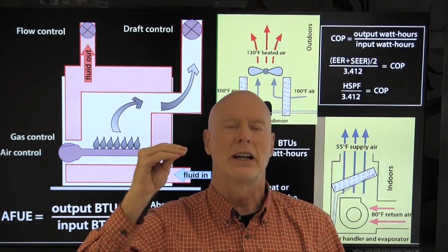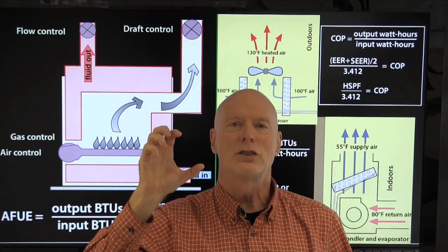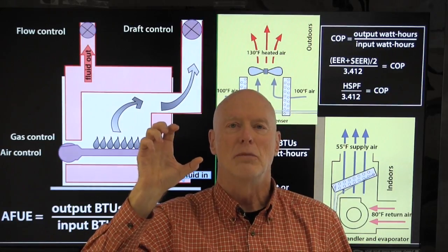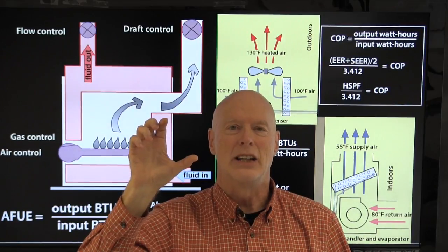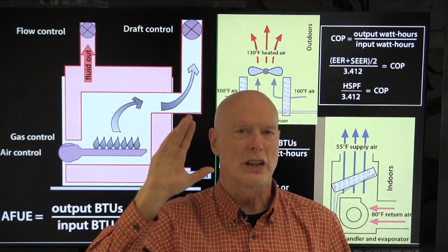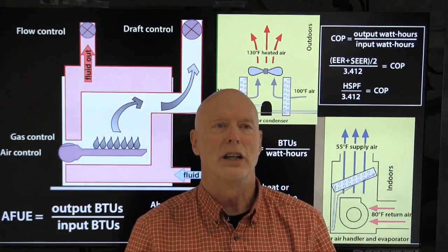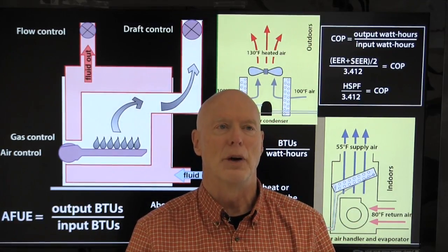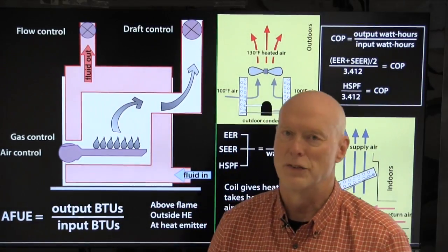The other thing that would indicate a kind of perfect efficiency is a very small temperature difference between the thermostat set point and the heating or cooling fluid. So just keep that in mind when I talk about the principles and the operation of these heating and cooling systems and how that affects the efficiency.